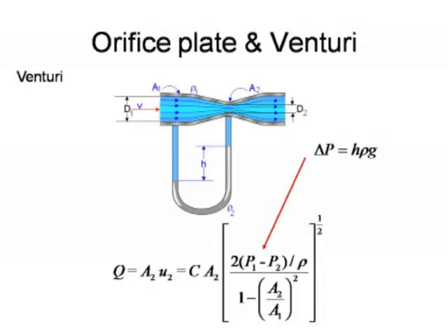So really if we do that, that gives us the pressure measured as a height of process fluid, normally liquid, flowing through the system, which is kind of a difficult concept because that means we're measuring the manometer height, h in the diagram, in terms of height of the liquid that's flowing through the system.